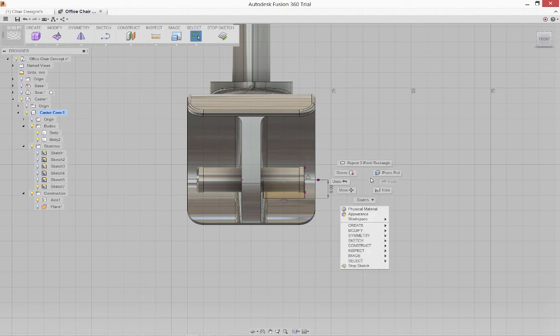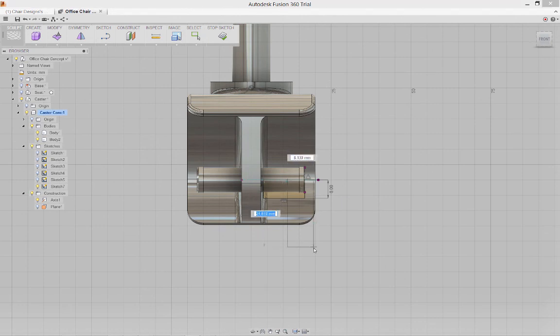So once again, I'll use the marking menu and just simply repeat that last command. Pick somewhere along the edge and overlap the two rectangles. I want to set the vertical height on this one to create what will eventually be a radius of 24 when we revolve our profile. And we'll set the width to be 10 millimeters.